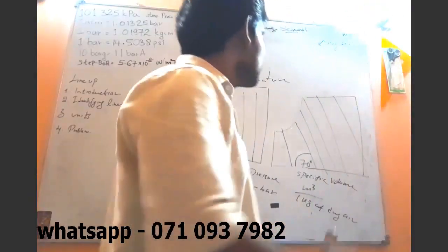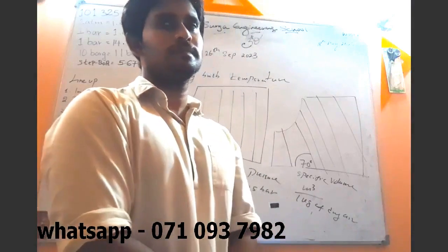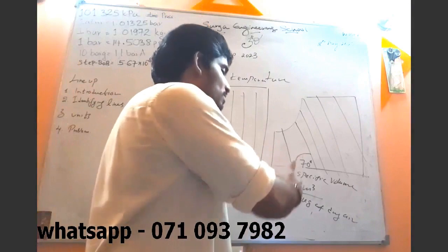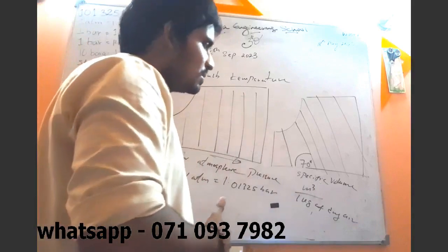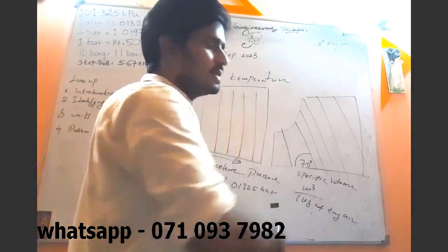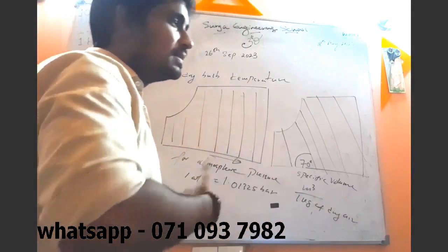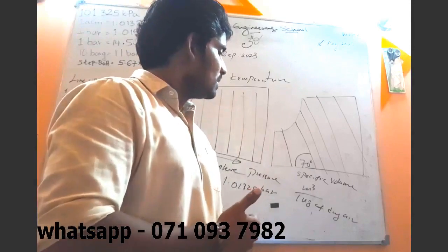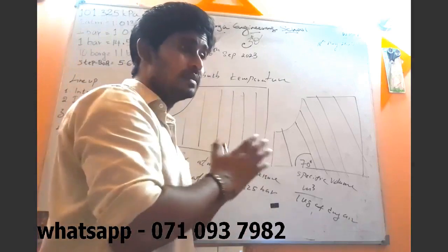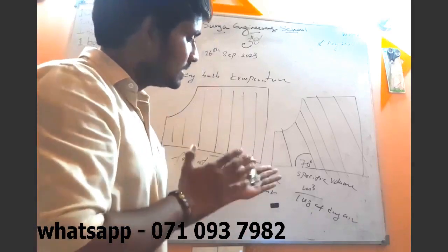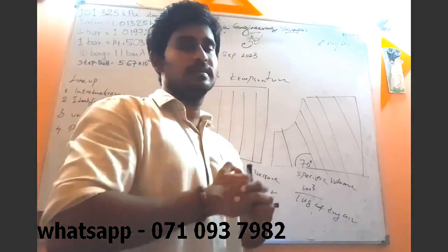Now here, the specific volume means the specific volume of the mixture, in meter cube per kilogram of dry air. Here I only teach you the meaning of these lines and curves. After that, when we solve a problem, you will meet the real life scenario. But the most important thing is that first you must know the meaning of these lines with correct units. So specific volume is actually the specific volume of the mixture.